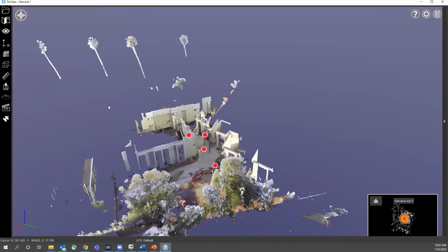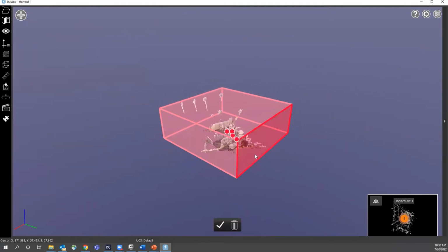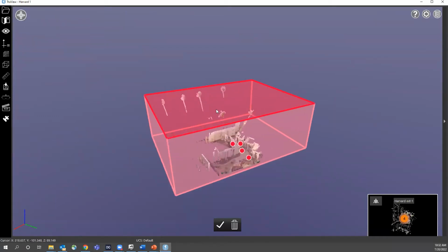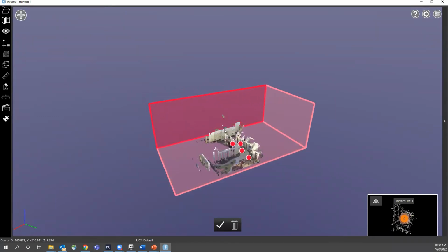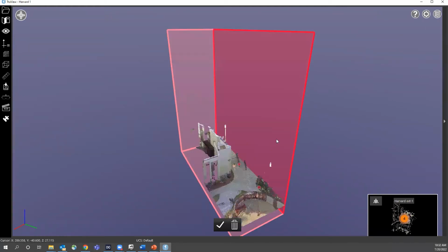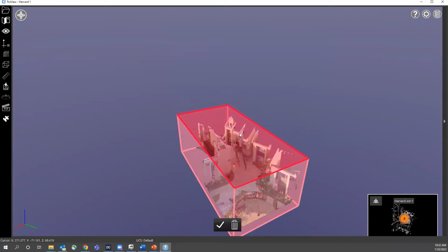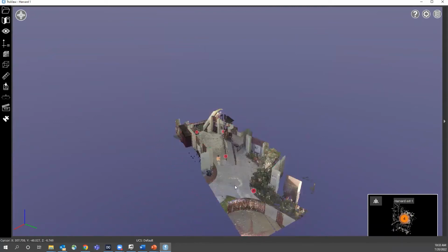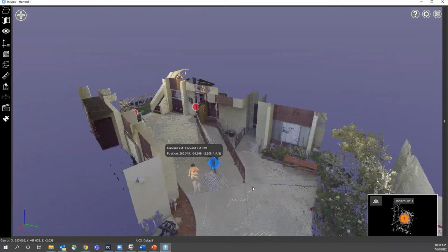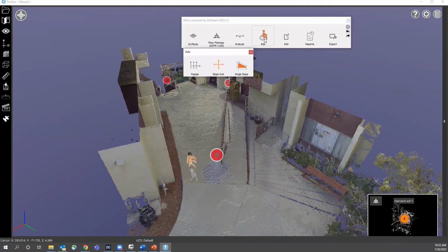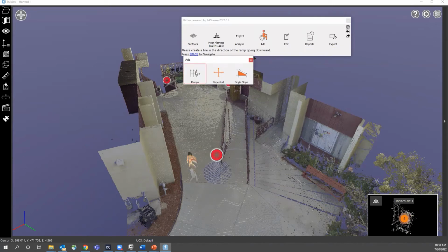But let's use the same data set, and now import that point cloud on top of your drawings and verify that those beams and columns are where they're supposed to be, right? Because if they're not, that's going to have implications further down the construction pipeline. This beam is actually 3 inches to the left and it's rotated 4 degrees. Well, now that's going to mess with whatever prefab I'm paying for, or maybe the MEP or the plumbing, where something's supposed to be going in that space that the column is now taking up. So the point I'm making is you're going to have so much information. Use these tools, but also think about all the other ways you can use the data. So I just want to add that.